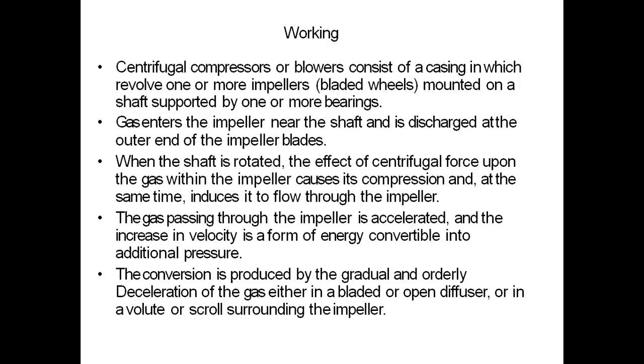The conversion is produced by the gradual, orderly deceleration of the gas either in a vaned or open diffuser, or a volute or scroll surrounding the impeller.